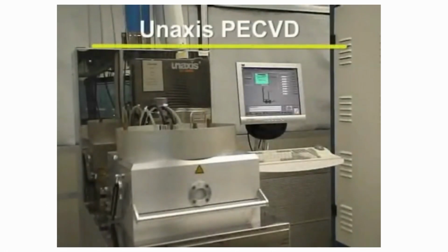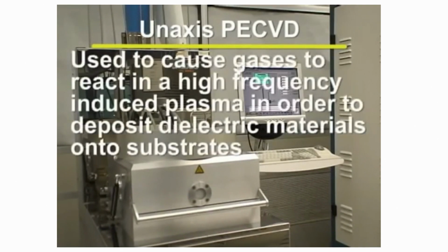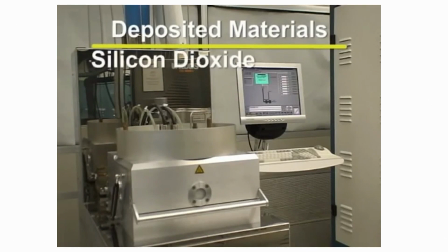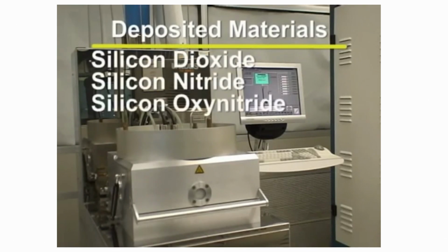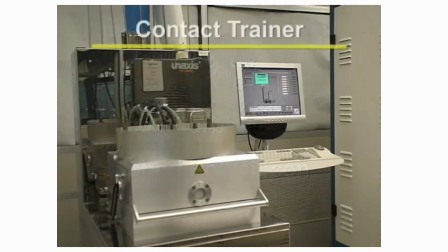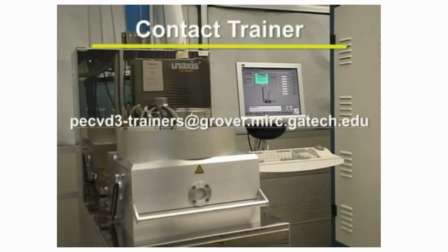The Unaxis PECVD, or Plasma-Enhanced Chemical Vapor Deposition System, is used to cause gases to react in a high-frequency induced plasma in order to deposit dielectric materials onto substrates. The Unaxis PECVD is a single-chamber system capable of depositing silicon dioxide, silicon nitride, silicon oxynitride, silicon carbide, polysilicon, and p-doped polysilicon. All users should contact the trainer for the system prior to depositing any type of polysilicon layer.